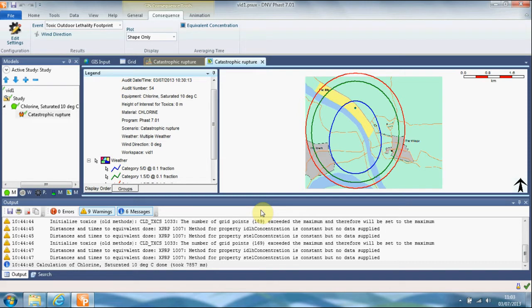So firstly, we must insert a time-varying short pipe scenario. There are two types of scenario available for modelling pipework rupture. There's the short pipe scenario, which models the release using the initial release rate for the start of the release, with a duration that is the time required to drain the inventory at this initial rate. This will normally give conservative results in the consequence calculations.